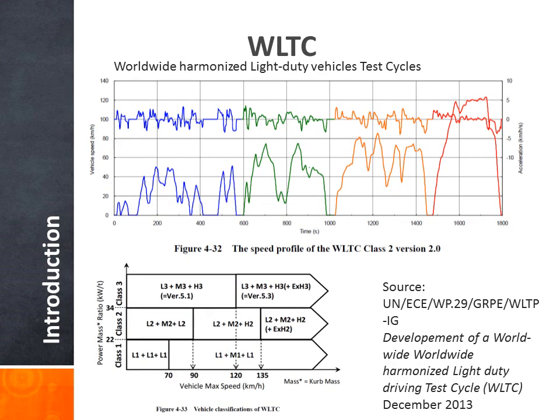Here, a Worldwide Harmonized Light-duty Vehicles Test Cycle can be seen, at least one of them. WLTC is designed to suit almost any light vehicle in the world, so there are different cycles for vehicles depending on their maximum speed and power to mass ratio.